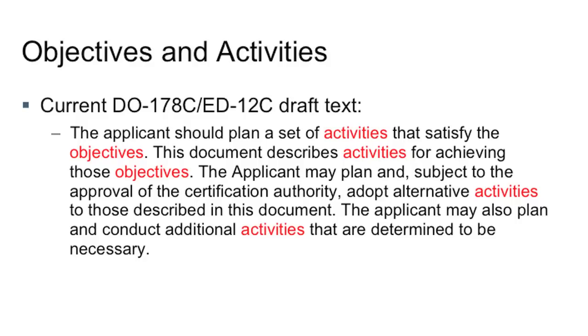So what we ended up doing was to say that in DO-178C, the document describes a set of activities for achieving the objectives, but you can substitute a different set of activities subject to approval by the certification authority, provided you can show that you meet the same objectives.